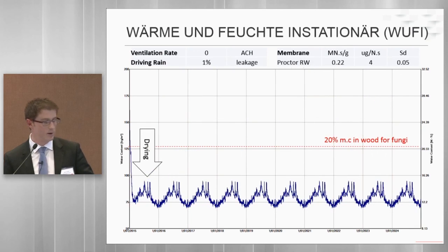If we then say, well, how do we design that system better by modifying the material layers and the vapour permeability of the layers, then with a good system, what you will see is drying in the first few months and stabilisation of the moisture content over the seasonal variations, which will stay below a critical moisture content, and therefore it's not likely to produce mould or timber rot.